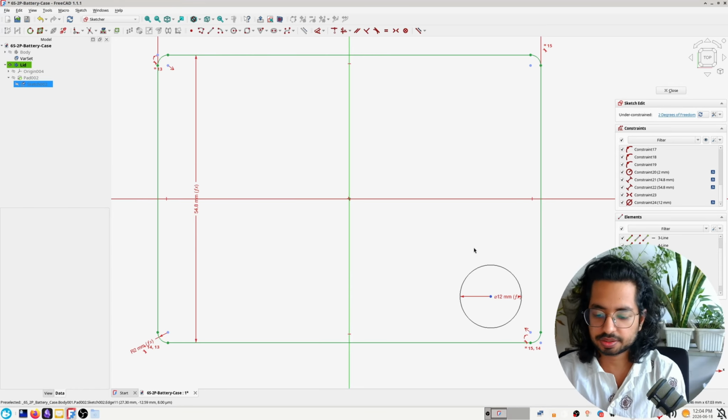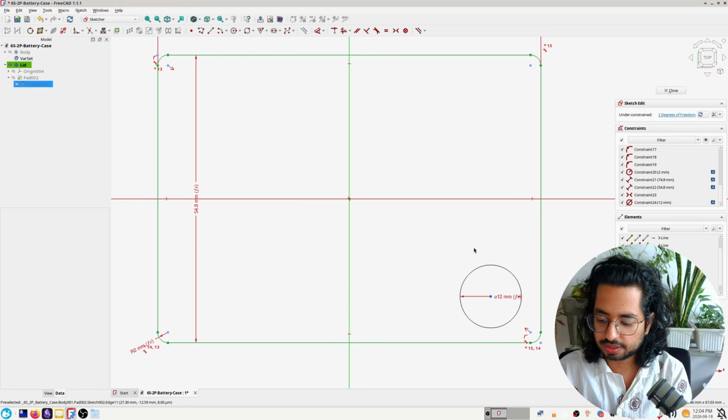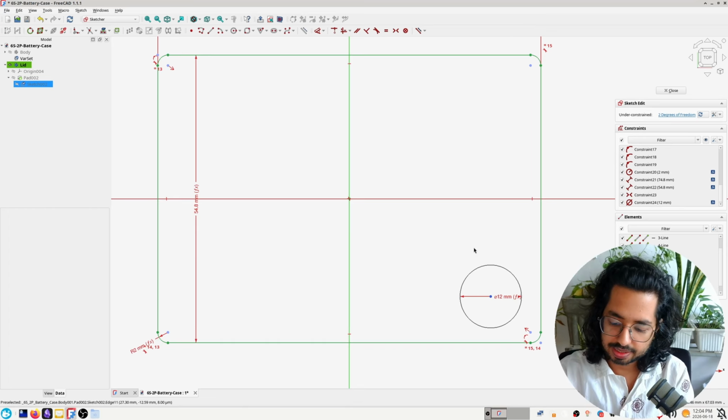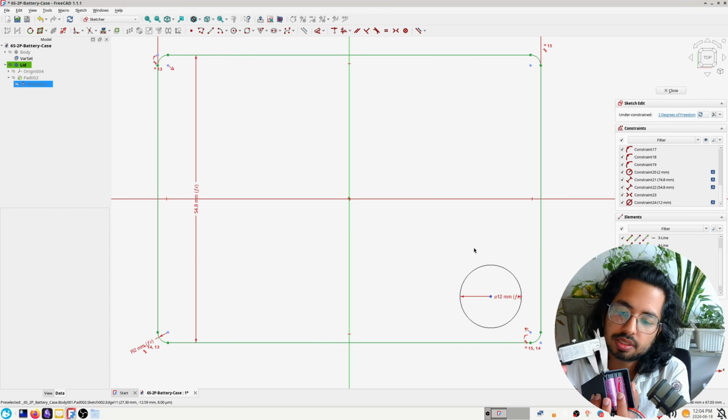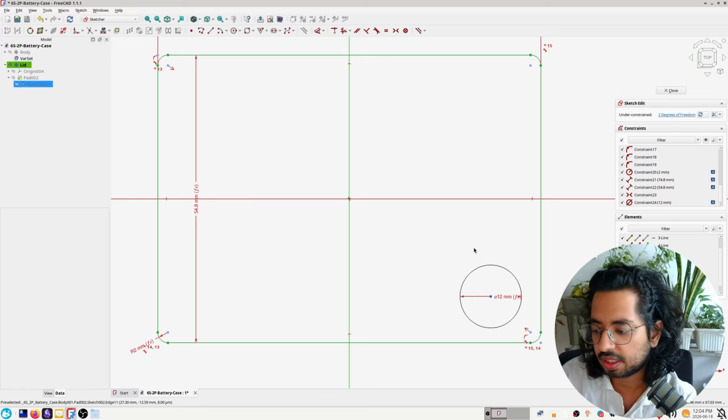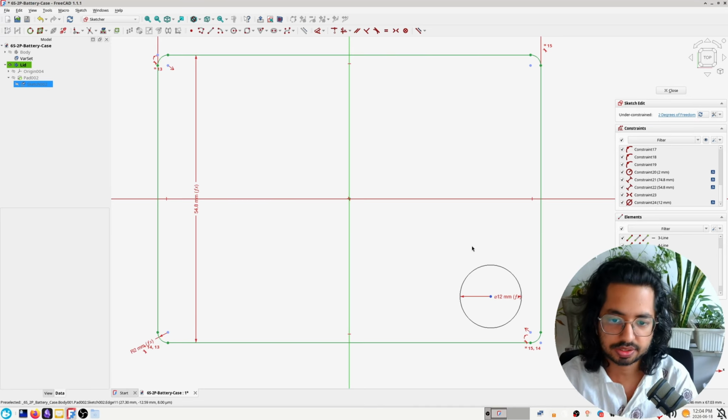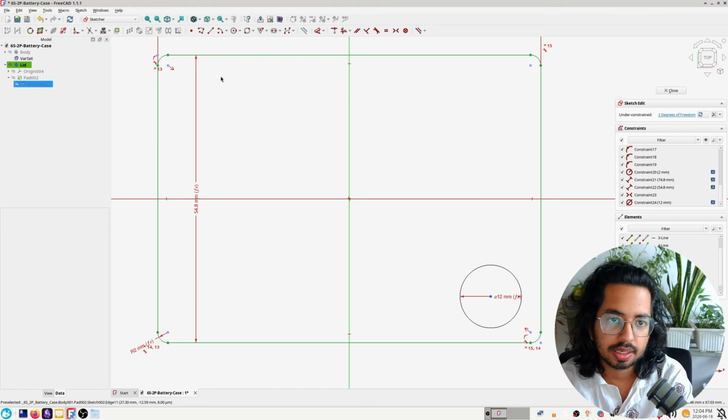So I'll measure the wire thickness, how much they need to be, and I'll make a slotted circle this time. My wire outer diameter is around 2.8 mm, so 3 mm. So let's think of the outer diameter as 6 mm. Okay, we get this slot. Click here and make it like this.